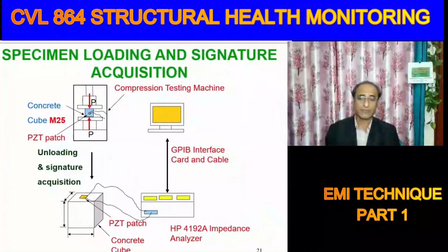This is an old study, done because prior to this the EMI technique was being used in the aerospace industry, and this was the first time we performed experiments on concrete, and we were not sure whether the technique would be suitable for civil structures like concrete or not. Here you see that we had bonded the piezo patch on a standard concrete cube, the kind used for compression tests, and after this instrumentation was done, the cube was loaded in the compression testing machine.